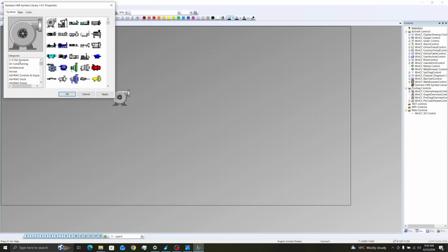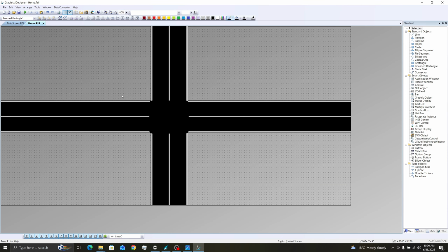Repeat the same process for the vertical conveyor symbol to create the north-south road. Finally, place a rounded rectangle at the center of the roads to represent the intersection. Disable the global color scheme, then change its background color to black so that it blends naturally with the roads. Our intersection is now taking shape.